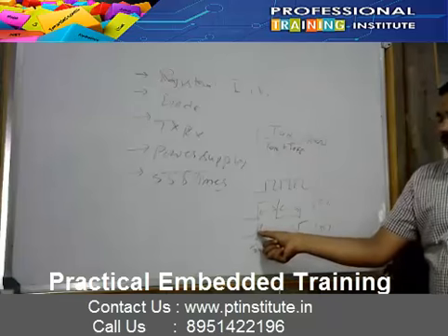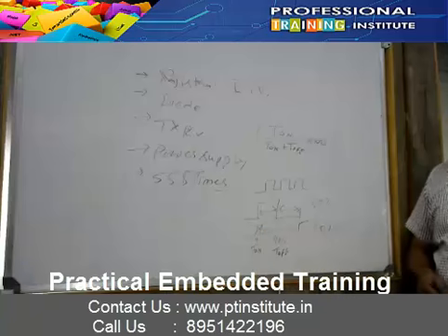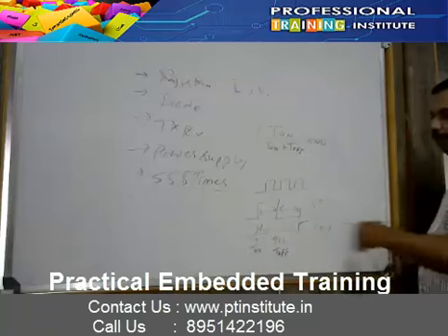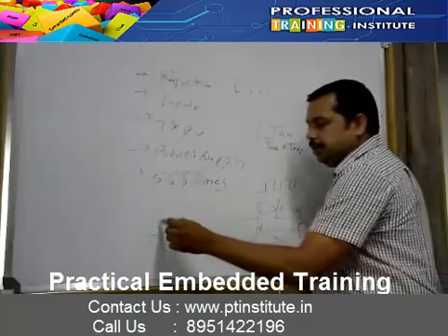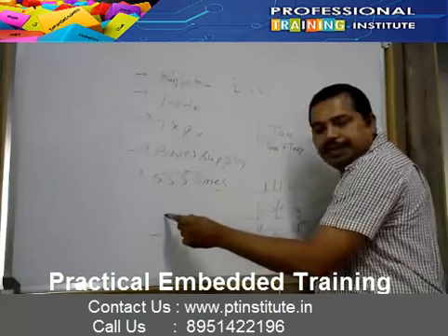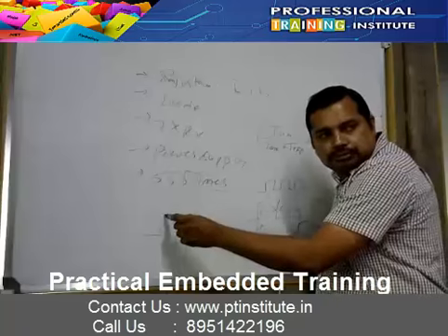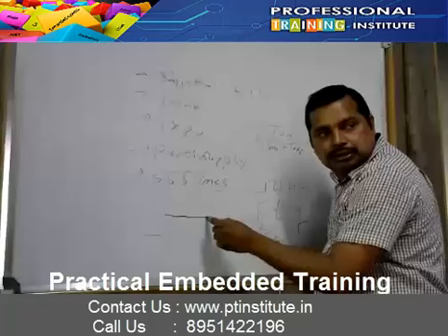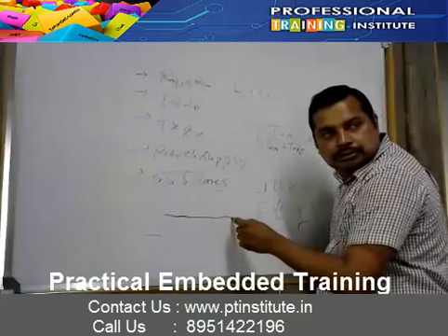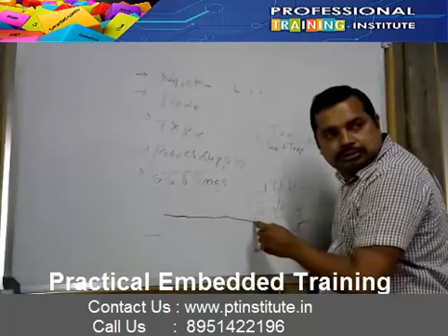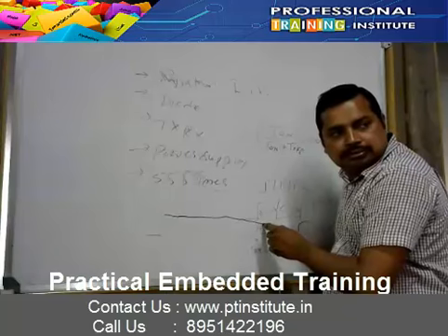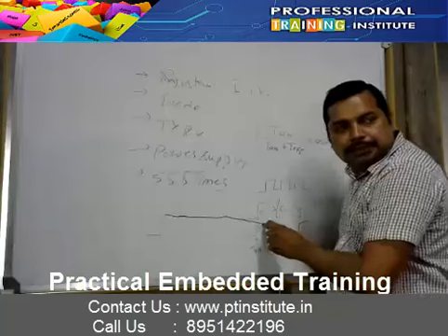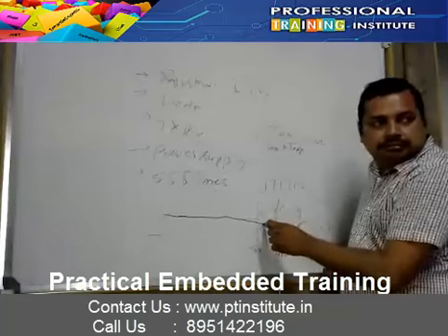So in this only 10% it is turned on. How to make 90% on? How to make a 90% duty cycle pulse here? Can you help me? Then for 90% duty cycle, decrease T off.